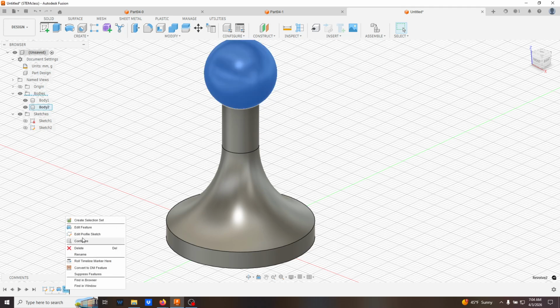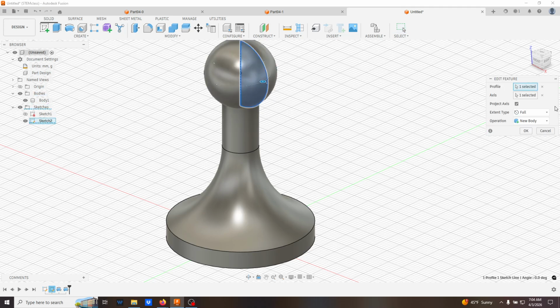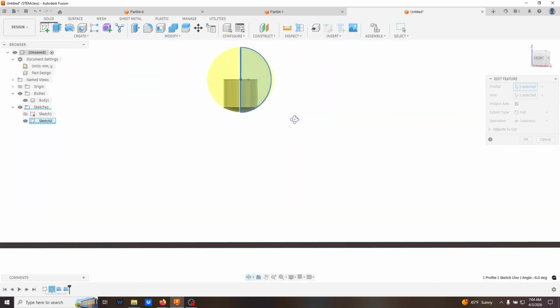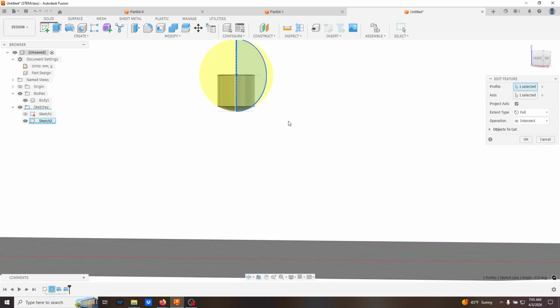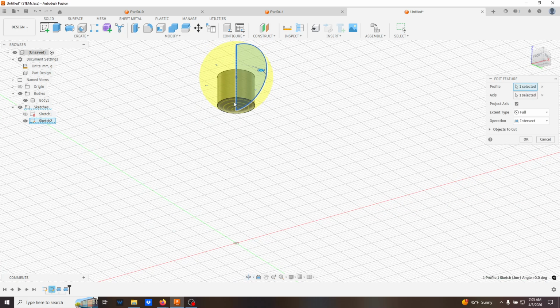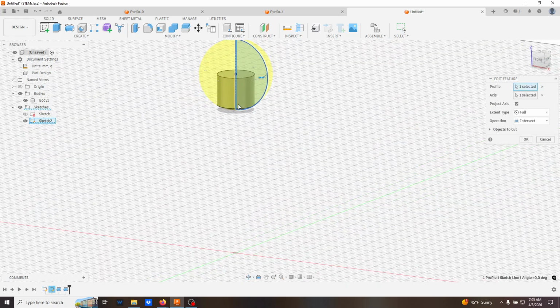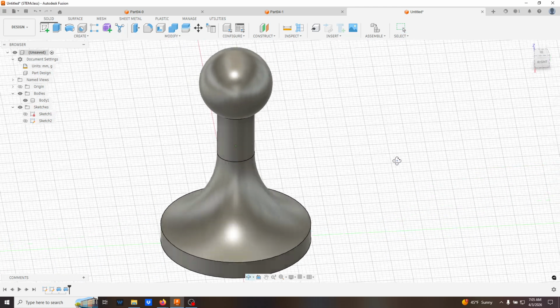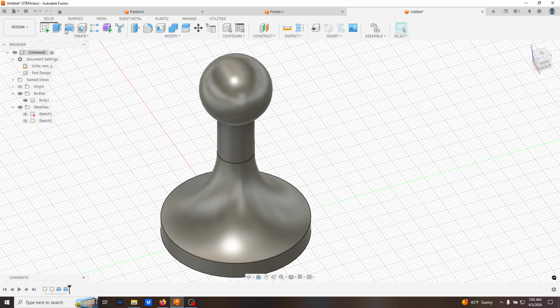And then, just to further highlight that feature, let me go here. We can also do an intersect, right? And that's going to give me the shape that overlaps. Intersects are really cool when you're trying to get combined surfaces or exotic shapes, because I'm trying to get just that piece. While I could draw that with a single sketch, in this situation doing the intersection of the two will give me this one. But I'll kick this back to join, and then we'll go here. Okay, so simple enough. Maybe clear as mud.